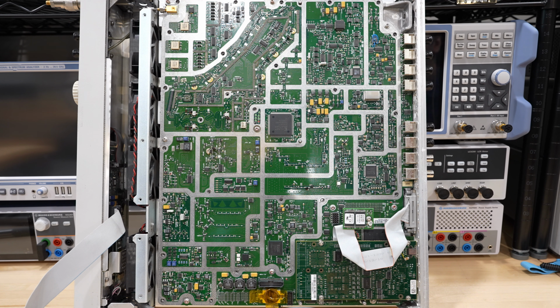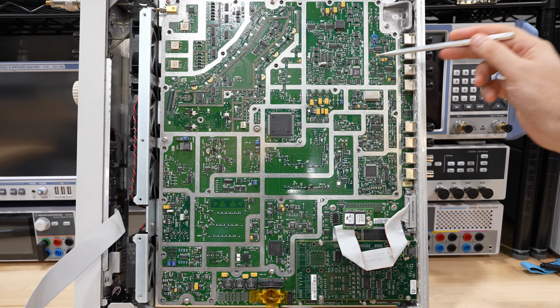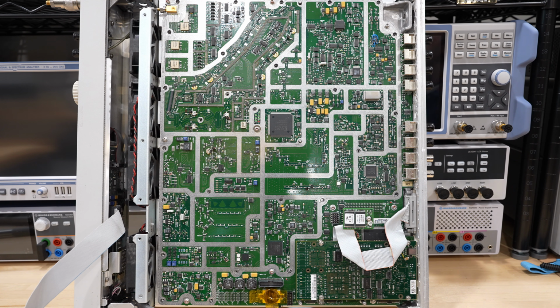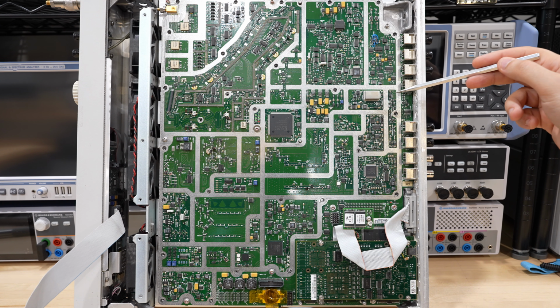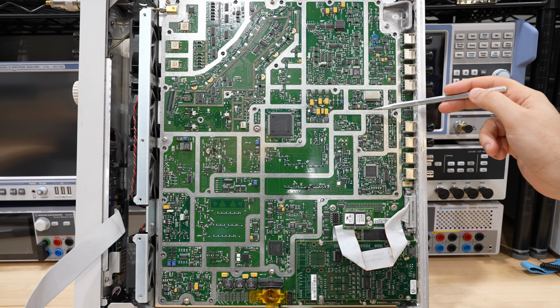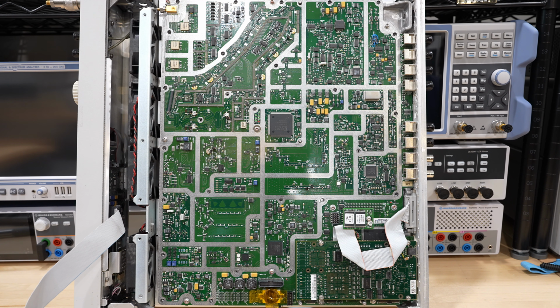So looking at it from the top, we can actually quickly figure out what each section is for. And then from there, we can hone in on the area we are interested in. We see over here sections responsible for that initial reference generator. Here's our TCXO, and there must be some over here, most likely on the other side, the actual oscillator, the 100 megahertz oscillator. So that portion is working, so we don't really occupy ourselves too much worrying about this section.